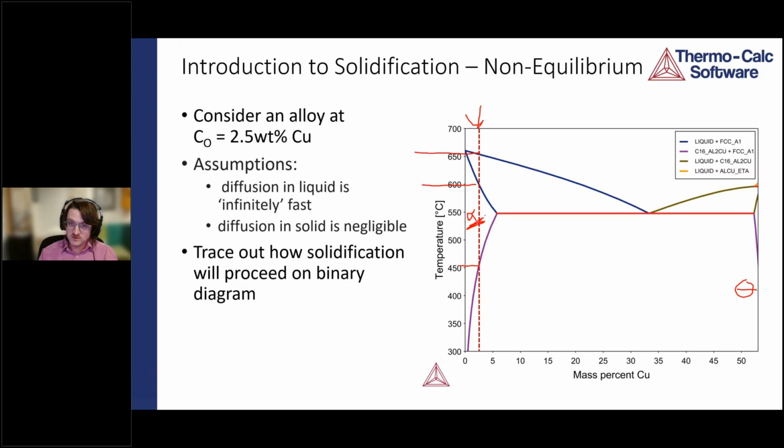If you were to cast it or weld it, you would be wrong. You would see in the microstructure that you have eutectic theta upon solidification. And if you were to measure the solidification temperature range through DTA or something, you would not see a solidus temperature of 600 C. You would probably see a solidus temperature of 550 C.